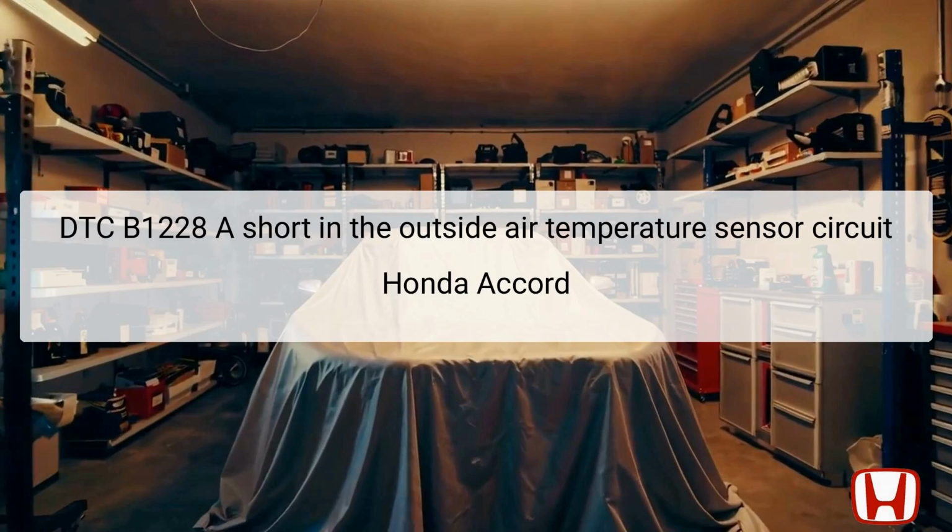The diagnostic trouble code B1228 indicates a malfunction specifically identified as a short circuit in the outside air temperature sensor circuit. This issue can affect the climate control system in your Honda Accord, leading to improper temperature readings and air conditioning performance. The outside air temperature sensor is located at the front of the vehicle, typically mounted near the grille. Its role is critical as it provides temperature data to the climate control system, which adjusts cabin temperature accordingly.